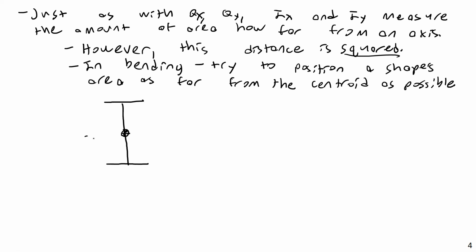And because this thing always ends up bending about an axis like this, in simple elastic bending, you'll typically have bending about the centroid. And that would actually look more like this. These would actually be plates, not just line elements. And these would be actual plates too. Something like this. But again, the basic idea here is to have as much of your area as far away from your centroid as possible, because that fundamentally is what creates bending resistance, at least in terms of material property.